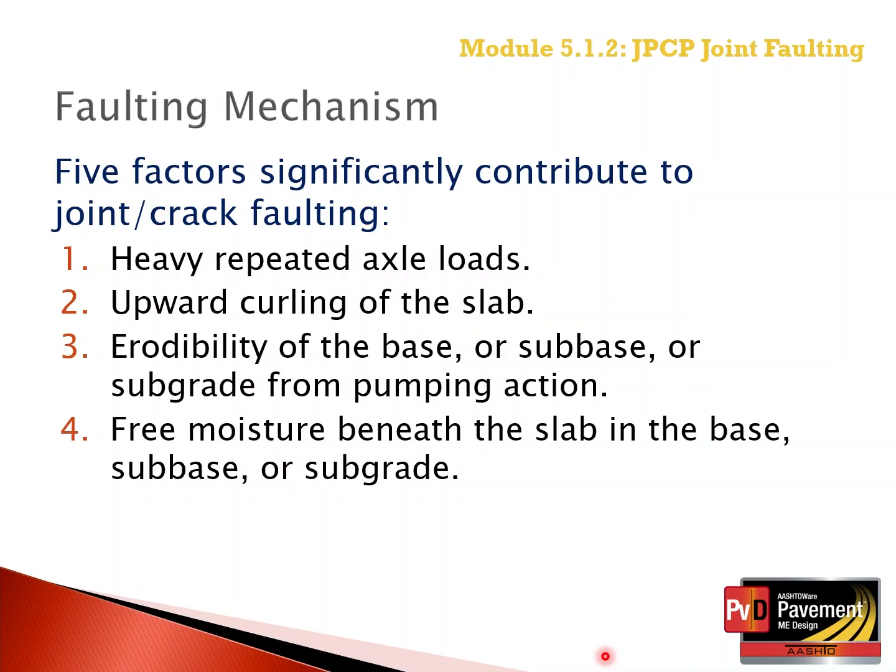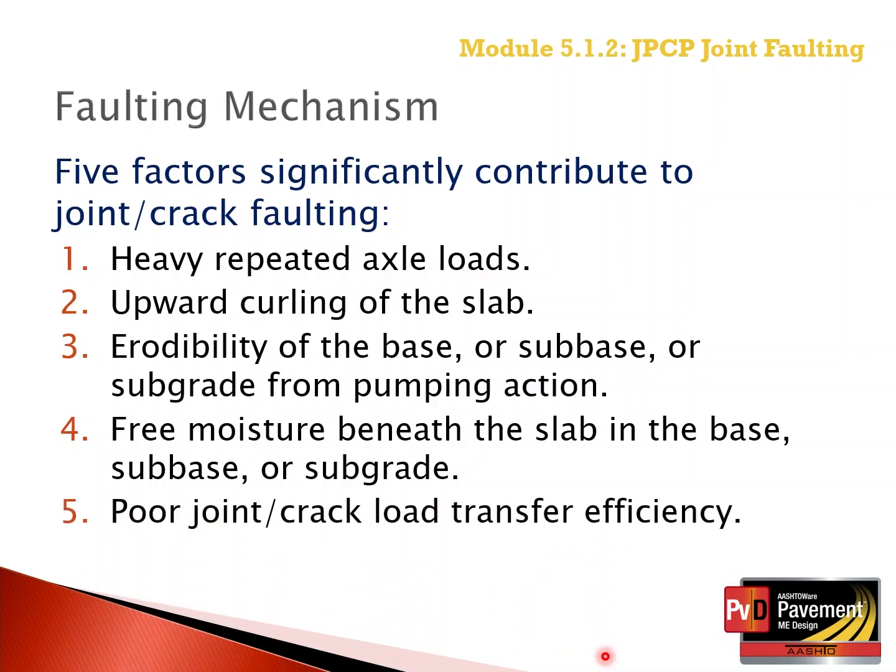In other words, the higher the water content of the underlying or supporting layer, the greater the faulting. The fifth is a poor joint load transfer efficiency across the transverse joint. Remember, the Pavement ME design software does not predict the faulting of mid-slab transverse cracks.